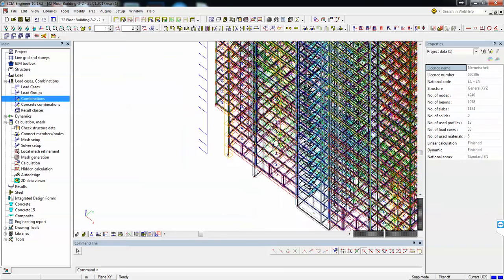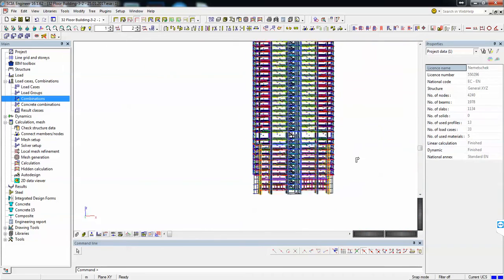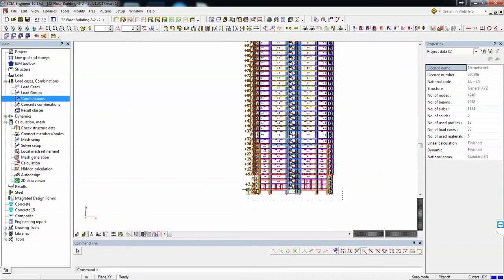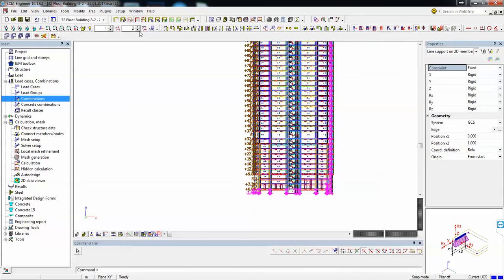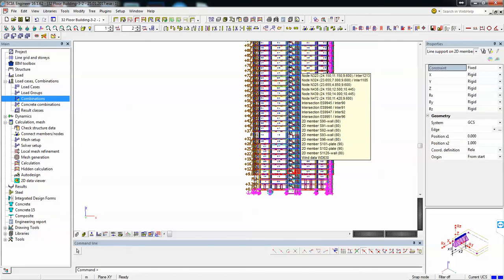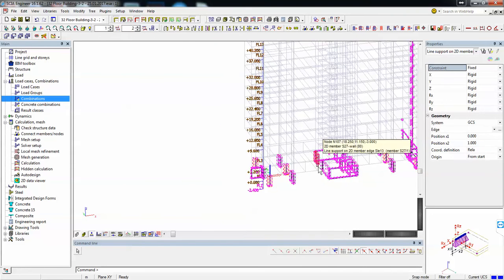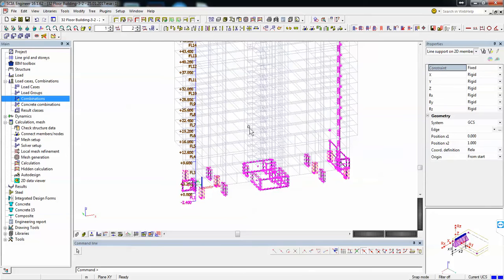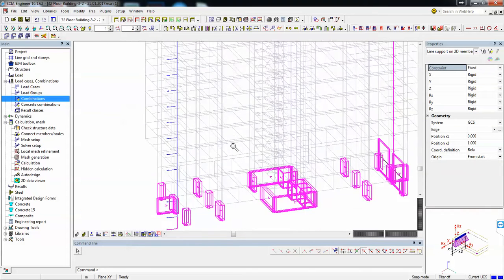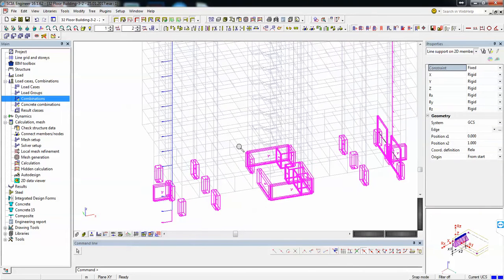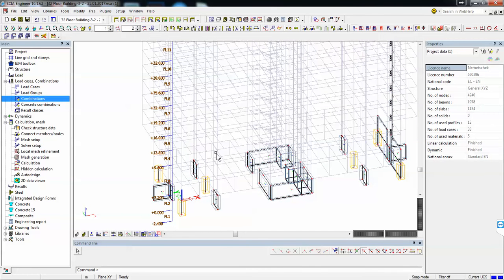let's say, model. So we'll first check the base, and then of course we can go with the reinforcement vertically. Although the bending moment will decrease, also the axial force will decrease, so it should be checked a few floors above as well, because the small axial force would cause smaller resistance. So we'll go back to concrete.